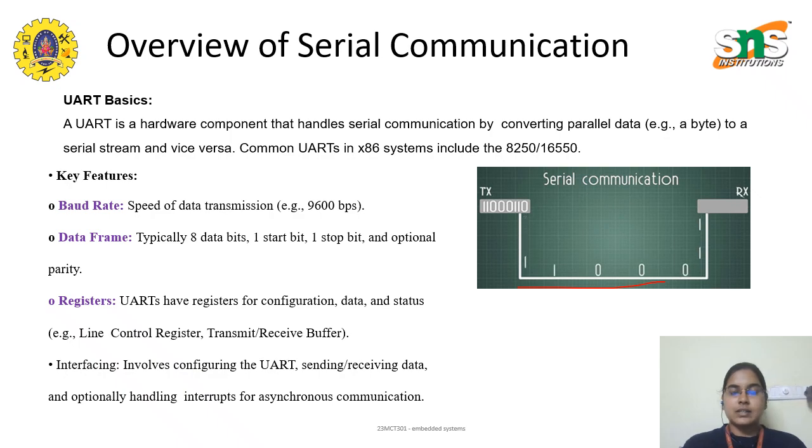So what is baud rate? It is the speed of the data transmission, and the data frame is typically 8 bits, with one start bit and one stop bit, and optionally a parity bit. And registers: in UART we have registers mainly for configuration data and line control, etc. Interfacing UART, we have to concentrate on sending and receiving the data, and optionally on interrupt handling.